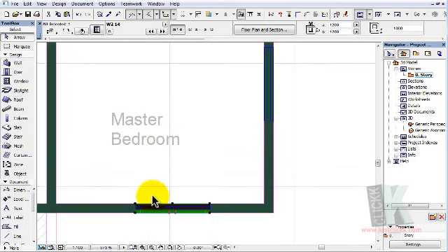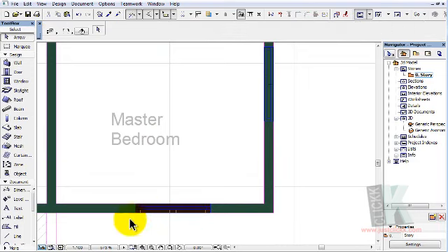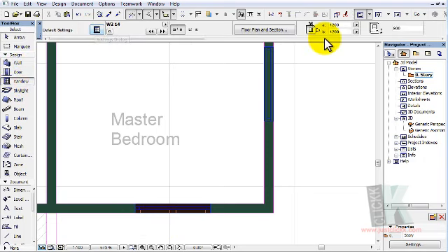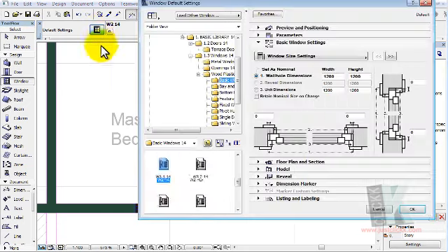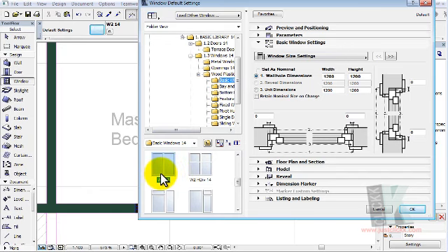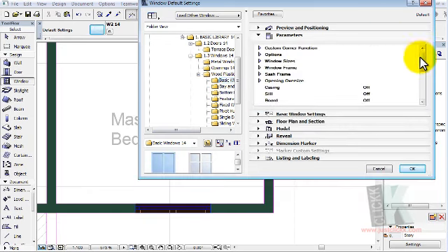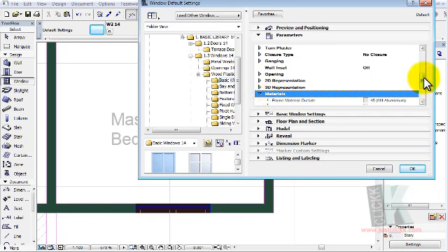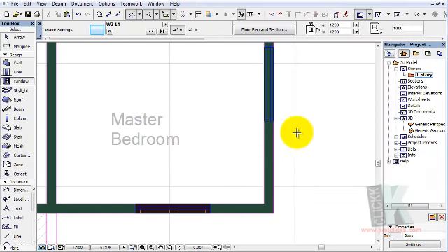So let's go ahead and using the same procedures we use in creating this window, we'll go ahead and create another one for the horizontal. This time around, let's just modify the settings here. This is 1050 and this is 1200. That's okay. And let's confirm if really is the window that is selected. Yes. And what about the parameters? Are we sure that the parameters are same the way we want? Yes. Then okay. And this time around, select this and then click.